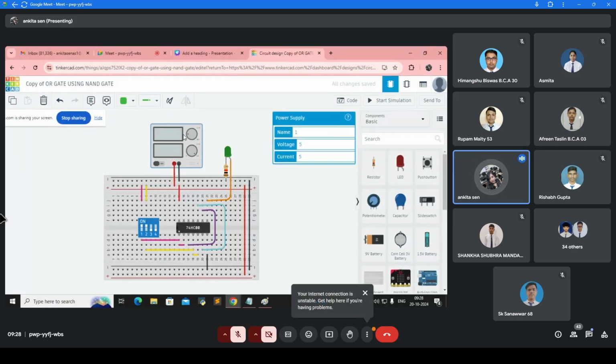And maybe I told you, did I tell you this? The power supply is something that gives you power, I mean to say voltage times current. In case of the battery, you don't have this much of an option. The power supply is a more advanced version of the battery, you can say. So what do you have to do? First of all, connect the negative pin to the negative side indicated line, the positive pin to the positive side indicated line, and connect both parts of this breadboard this way.